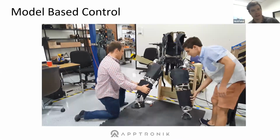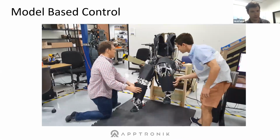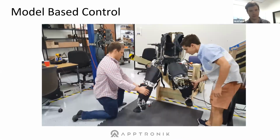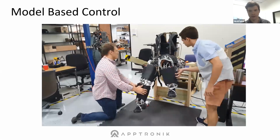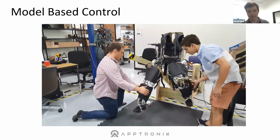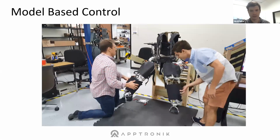Moving forward chronologically, this is a bring up of the full system, focused here on the feed forward control portion of the system control. So as many of you are probably familiar with, this is just a gravity compensation controller. The hip frame of the system is grounded in this case, but given the torque controlled actuators, you're able to do pretty good gravity compensation with the device.